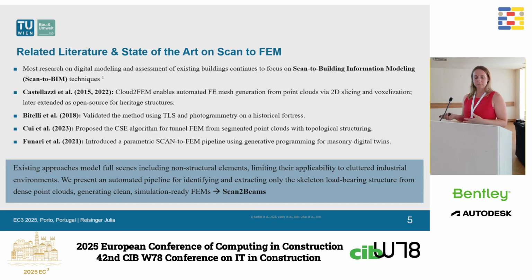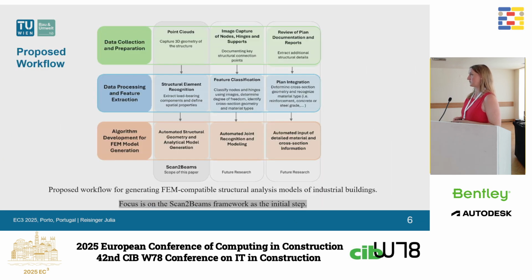These existing approaches are usually modeling full scenes and often including non-structural elements, having walls, however industrial building structures have these skeleton structures. And when you go into an industrial environment, you have a lot of noise in the point clouds with pipes, with production machines, there's a lot of things going on, and so we need to filter out. And this is what we're doing. We are now presenting an automated pipeline for identifying and extracting only the skeleton load-bearing structure from the dense point clouds to generate clean, simulation-ready FEMs, and we call it Scan2Beams as a first approach.